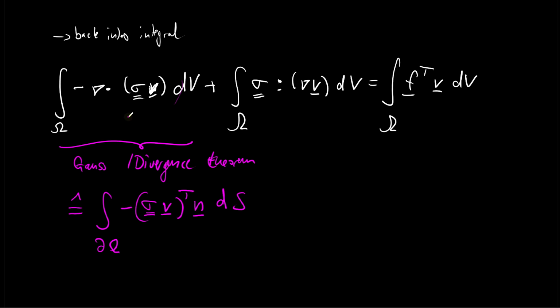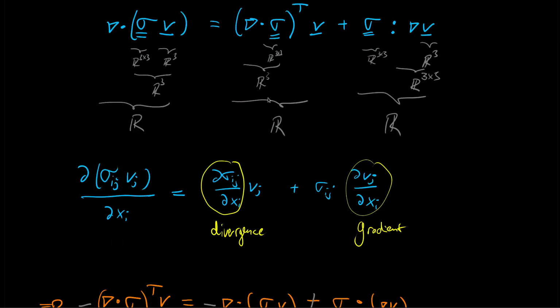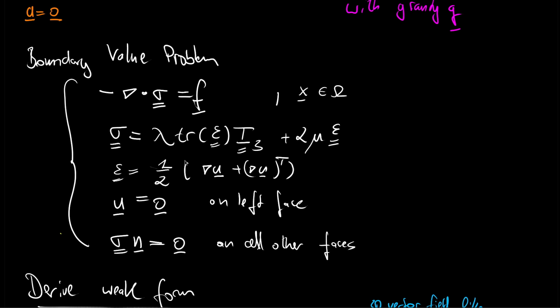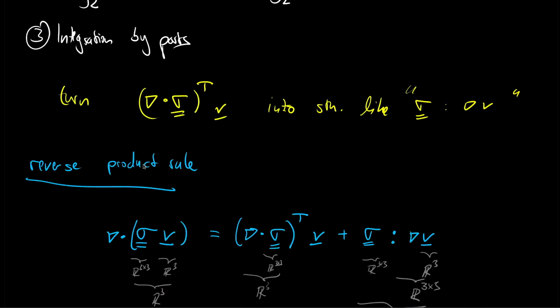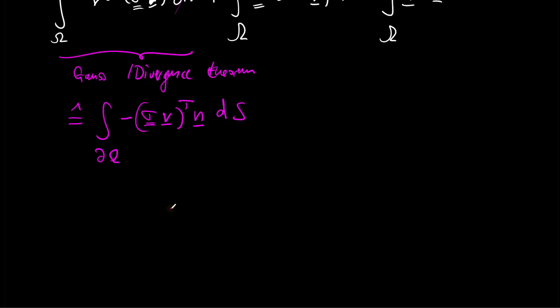And this now helped us with this theorem to also avoid the spatial derivative again. And now we only have one spatial derivative on our primary unknown u. As said, it's a little bit hidden because the sigma already contains one by the constitutive laws and by this displacement strain relationship, but at least we now have a preliminary weak form, which I want to note down.